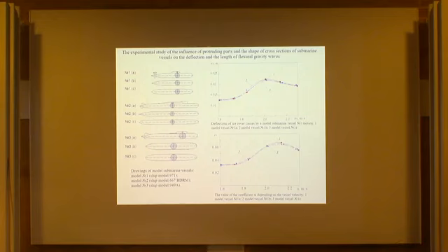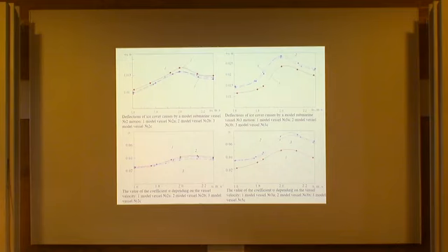The given paper presents experimental research on the influence of the form of contours, the form of cross sections, and the presence of protruding parts on the deflections and the length of flexural gravity waves. The results of the studies show that the use of simple submarine vessel models instead of models of a real ship is not always expedient.